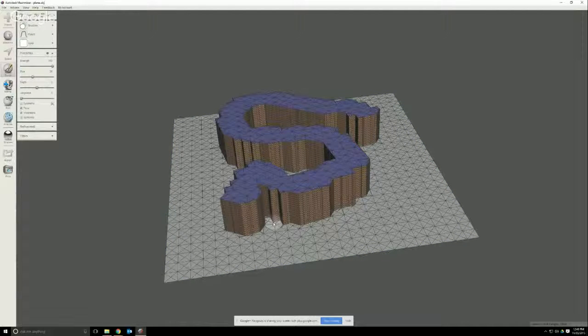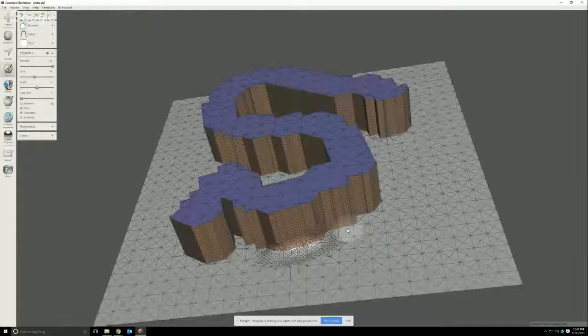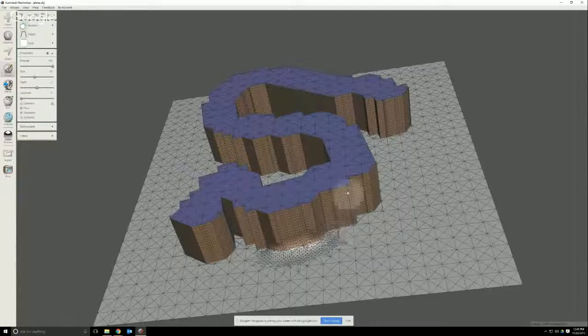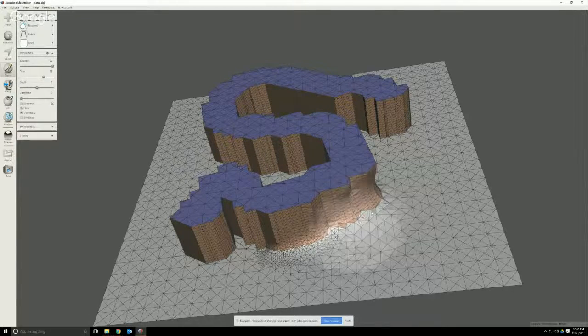I'll do robust smooth. So robust smooth, what it does is it kind of balances the smoothing between all densities inside of the cursor. What this does is, if I've made this very large, it's taking the smoothing that you would need for this very loose area and balancing it with the smoothing that you would need for this, so that you get a nice smoothing effect.